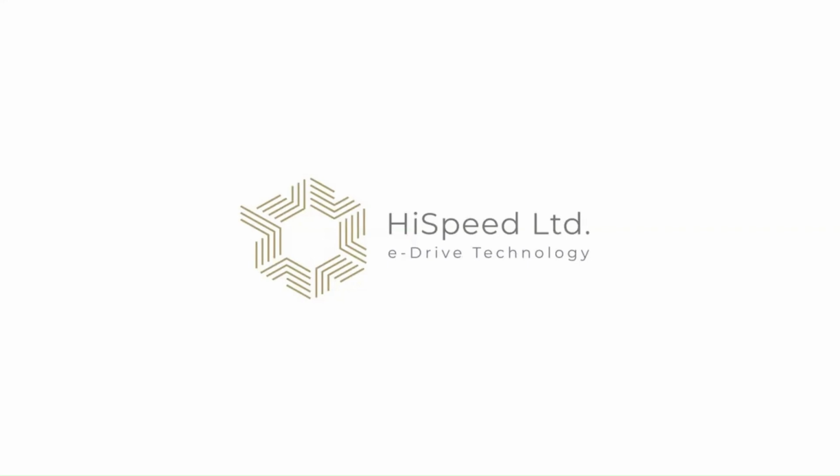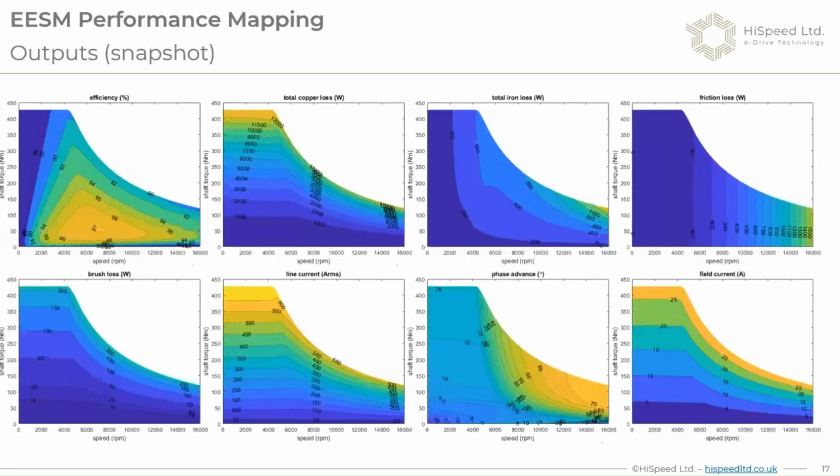Well, usually, you know that the PWM induced losses are usually maximum for a modulation index of around 0.5, depending on the modulation that you use in the inverter. But usually they are maximum around that value. So what we do is we pick a point where we use 0.5 modulation and calculate the losses from there, and then use a function to extrapolate them.